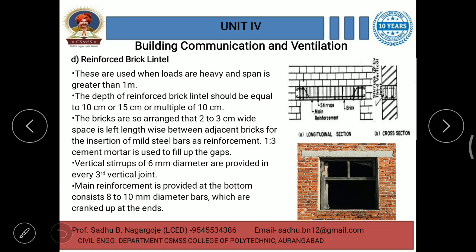Then the fourth type, reinforced brick lintel. Okay, these are used when loads are heavy and span is greater than 1 meter. Okay, you have to compare this type to the previous one. So it is for a heavy load and when the span is greater than 1 meter. The depth of reinforced brick lintel should be equal to 10 centimeter or 15 centimeter, or in multiples of 10 centimeter.